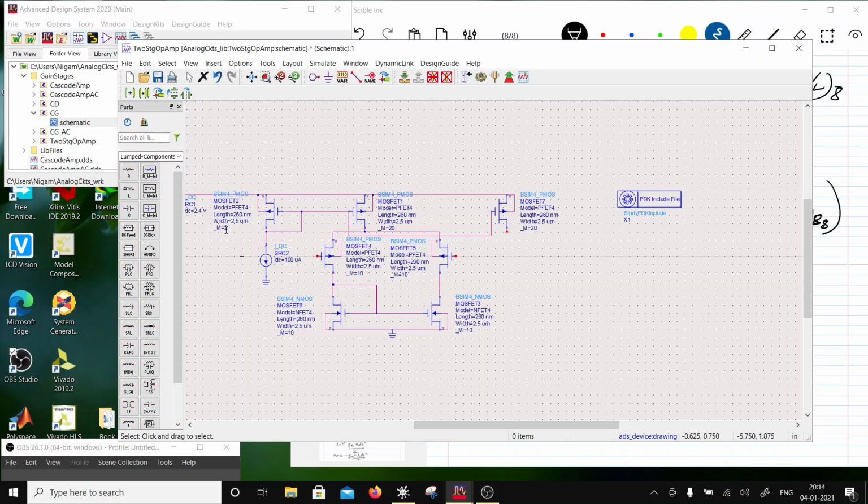So how about I do the following: I do this as 4 and this is 40. So this is still 1:10, and this one remains 20, and this one remains 20, and this one remains 10 and 10, half of that, and then the other transistor is going to be twice of that for systematic offset voltage. So this is going to be 20. Now having done that, let's see how this scales. This is going to be still half of that, so that's okay.